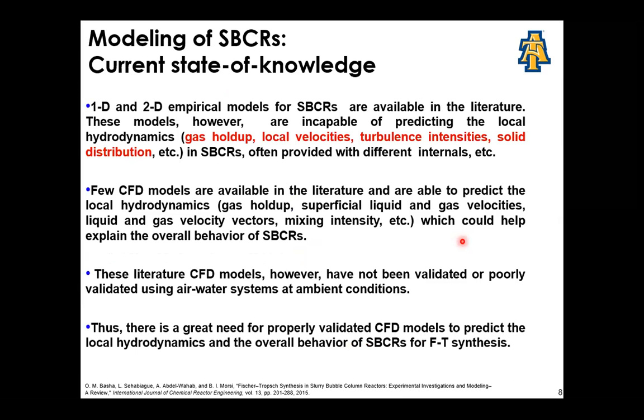All right. So let's state the current state of knowledge we have about the modeling of slurry bubble column reactors. One-dimensional and two-dimensional empirical models for the slurry bubble column are available in the literature. These models, however, are not capable of predicting the hydrodynamics, which are the gas hold-up, velocities, and solid distribution in slurry bubble columns, often provided with different internals.